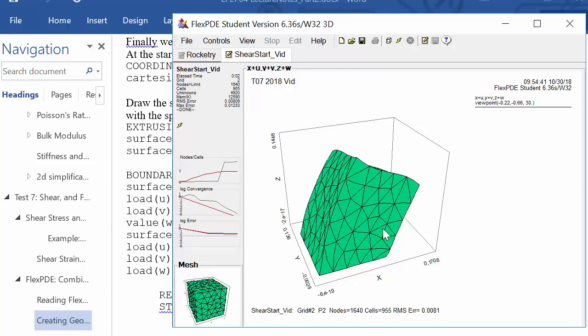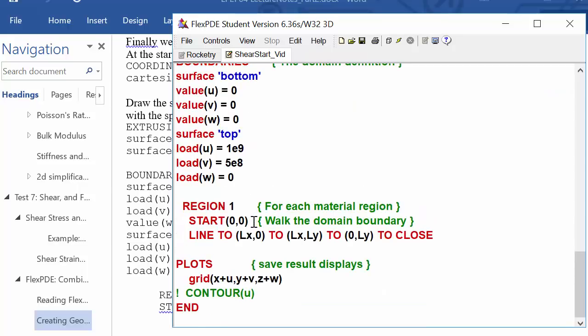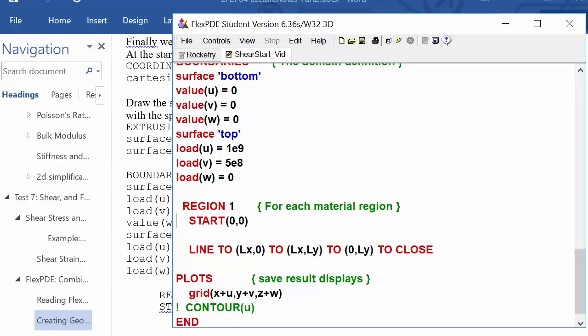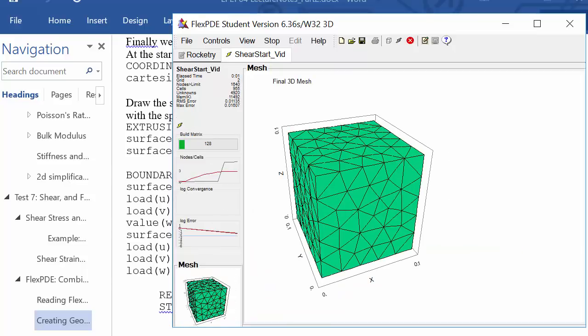To get it into pure shear, we're going to need to also specify the boundaries on the sides, and this is a little bit tricky. Whenever you specify a boundary, these boundary conditions still exist until you specify another one. So we can specify a boundary in between these different sections. First, let's just add in the keyword line here, which is implied if you just have this point and then a 2 immediately afterwards. So if we do this, then we shouldn't have changed anything.